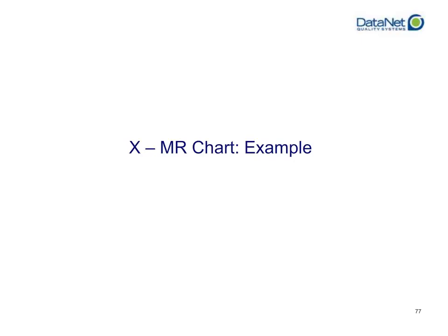Keep in mind, though, that it's probably not ideal to use these X and MR charts unless you have a specific need to do so. Generally speaking, you usually want to have a subgroup size greater than 1 to eliminate noise within your process. But we're going to go ahead and do an X and MR chart example right here.